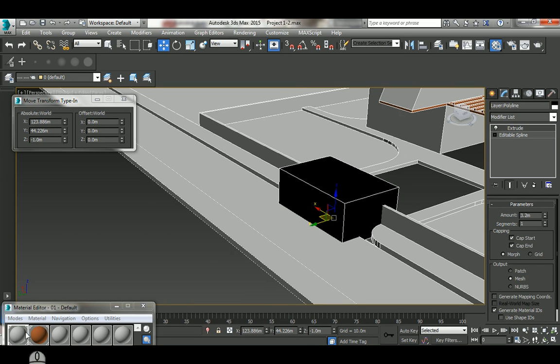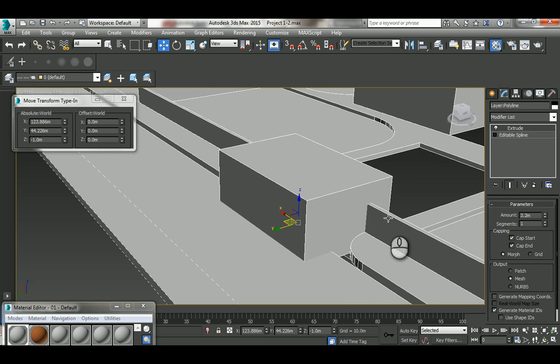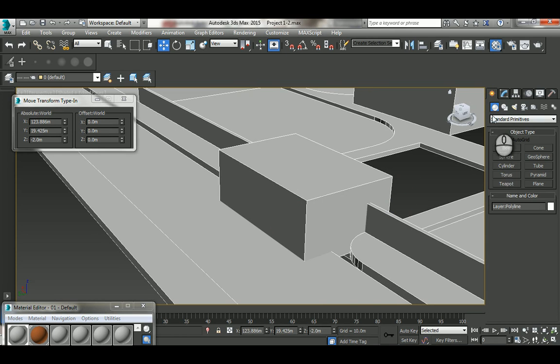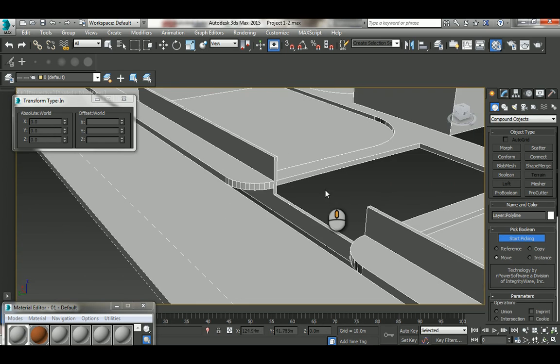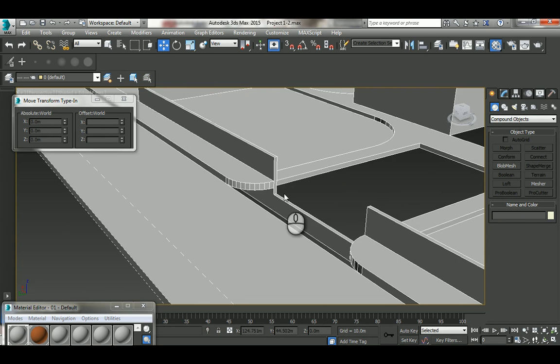It's a good idea to add any type of material, specifically the same material that you're gonna use for this wall, before you make any boolean or pro-boolean. Otherwise you're gonna end up with edges that have a black or some different material. So now I cut it off, as you can see. Now I will model this part of the street or paved area within the house.